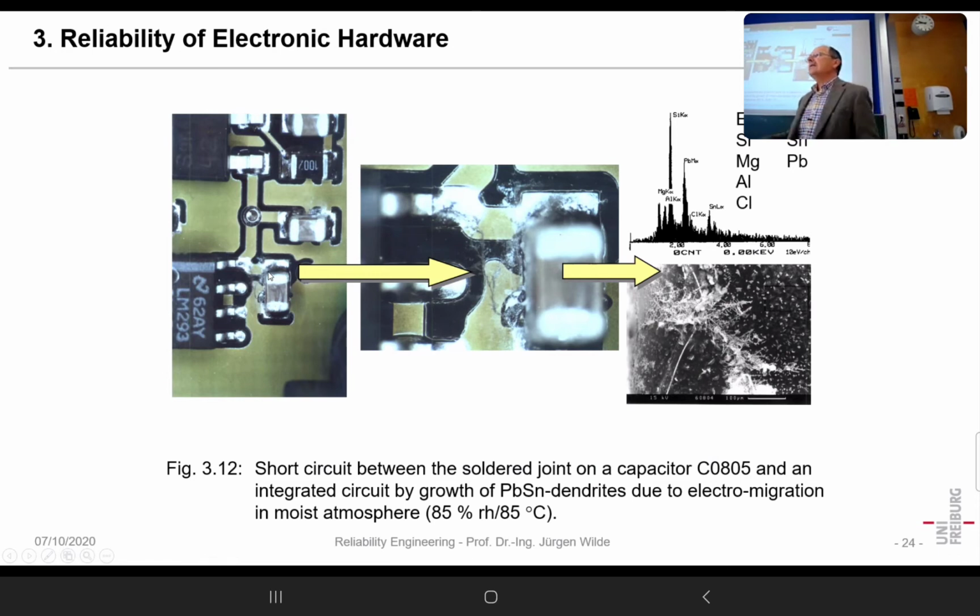And here, the following thing could be observed. These devices, which again were ECUs, were operating for some time in that moist test environment, and suddenly they had a fault. They were reset and working again. And after some time, the same thing happened again.